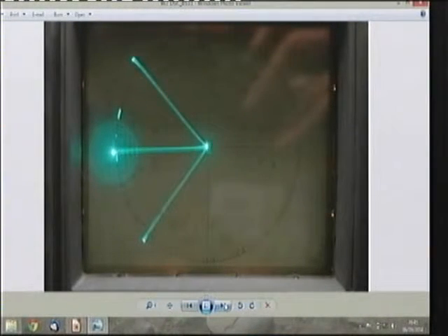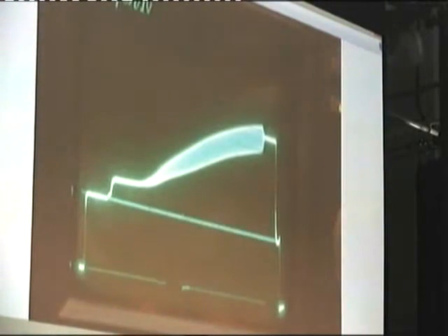Click. This is the display on the vector scope, as you would see it. I've turned the vector scope gain up here, and those are the burst, and that's the subcarrier on the sawtooth in the U-axis. Click. And I had to search quite long to find an amplifier this bad. You can see there that this has plainly got differential gain. What this means is that the gain of the subcarrier changes according to the amplitude of the video. Not what you want. Hard to fix.